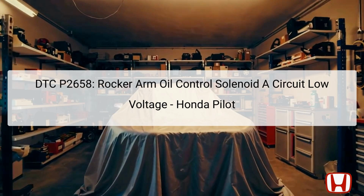The DTC P2658 refers to an issue with the rocker arm oil control solenoid A for bank 2 in the Honda Pilot, particularly in model years 2016 to 2022. This DTC indicates a low voltage condition in the circuit, potentially impacting the performance of the variable valve timing and lift electronic control, VTEC. The rocker arm oil control solenoid plays a crucial role in regulating oil flow to the rocker arms, which is essential for proper timing in engine operations.